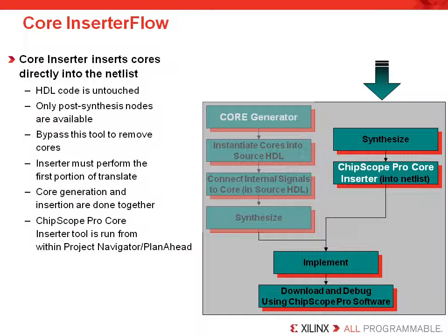After the user uses the core inserter to specify the post-synthesis nodes to be probed, the inserter will perform the translation phase of the implementation. This is necessary because in the code generator flow, the cores are inserted as a netlist. The flows were designed to be tightly integrated into the ISE tools and PlanAhead.